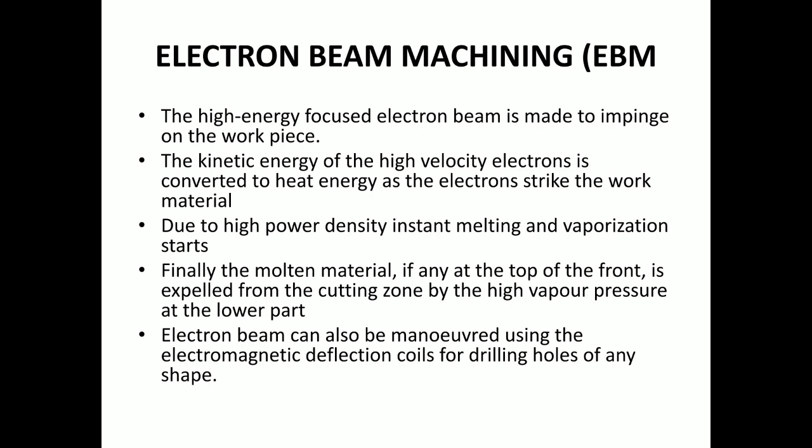Due to high power density, instant melting occurs. Third point, melting and vaporization starts. Finally, fourth point, the molten material, if any, at the top of the front is expelled from the cutting zone by high vapor pressure at the lower part. This I have explained to you.